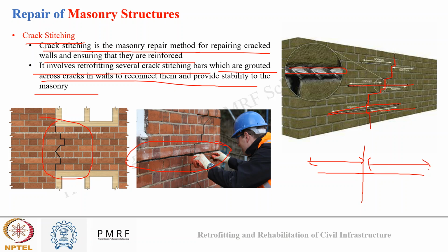Here you can see they have used 500 distance. Now based on the severity of cracking, you can increase or decrease this distance. Suppose you see a very fine crack, you can lower this distance from 500 to 100 also. But if you see a very wide crack, you can increase this distance.